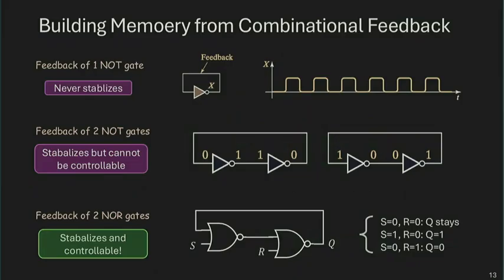So to build sequential circuits, we do need combinational feedback, a way to bring back some of the previous information back to use. And there are several ways you can attempt to build this feedback. The first approach is to take a single inverter and then connect the output to its own input. Now you have a feedback, and data can flow within that singular inverter again and again.